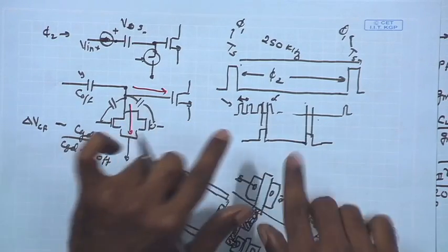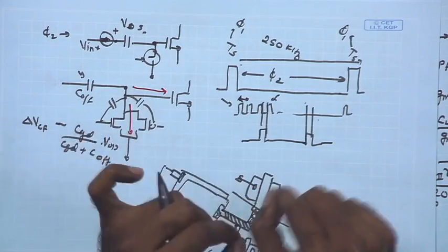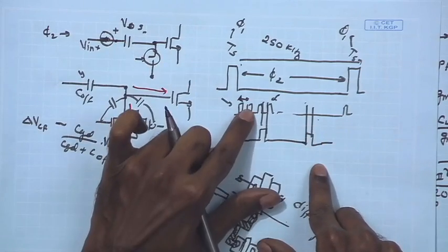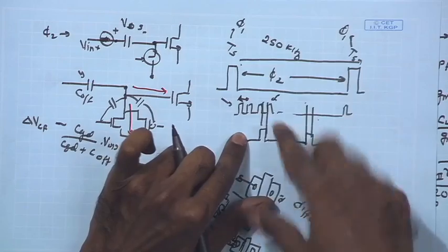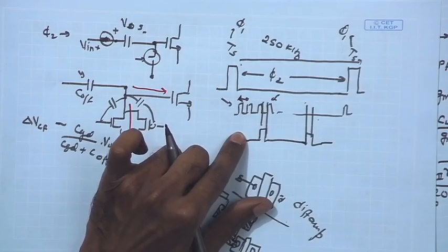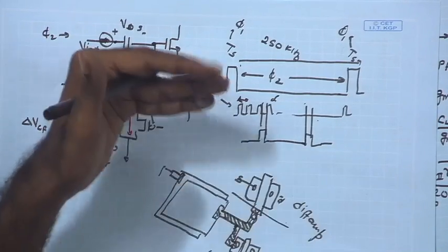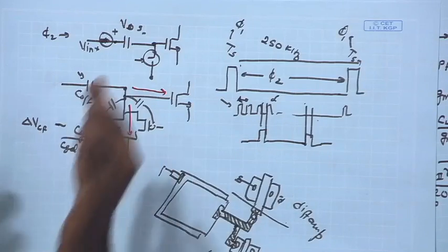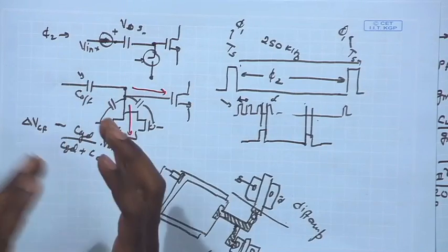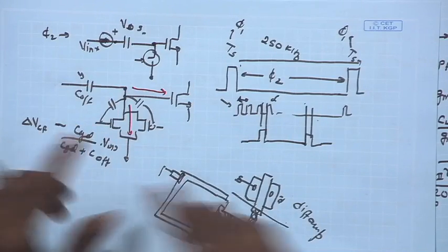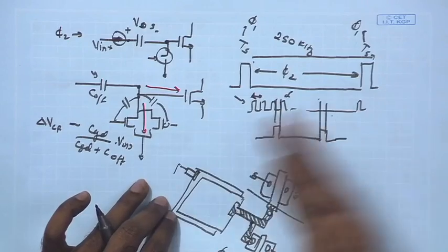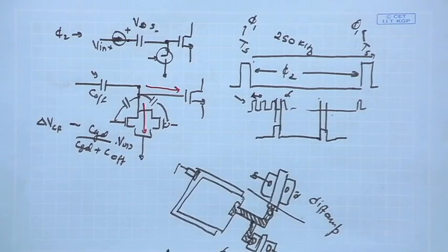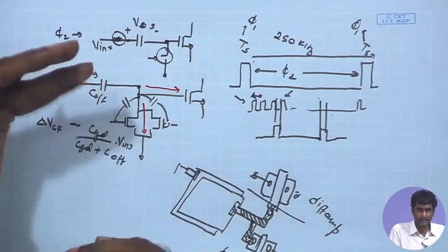So, you can see how the circuit operation or the circuit level results can impact our control scheme: when to apply the phi 1 pulse, how many phi 1 pulses to apply, and then accordingly what the digital control scheme is. All these things get linked together very tightly. If you are messing up some circuit implications or metrics by making this amplifier faster for the closed loop feedback, we may be dissipating more power over there, or making the design more complicated.